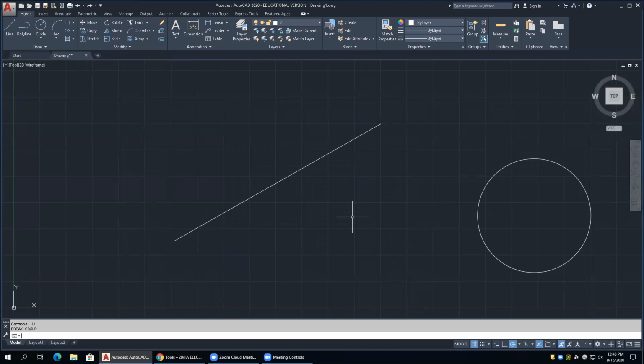So we can be specific, and we can also force the break differently. Okay, so here's how we can do this. Let's go back into the break command. So select your object. Now notice there's a first point object down there as an option. What we can do is say, I don't want the point that I selected as my first point. Okay? I'm going to force a first point by using something different. So what I can do is hit, okay, first point. And then it's going to say, okay, show me or specify the first breakpoint. I'm going to hit a shift, right click.